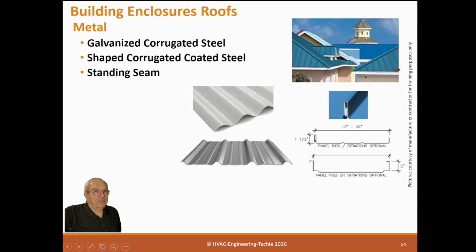They are very durable except for hail. Now, hail doesn't damage the metal, but what it does is it damages the surface. When it hits, it forms a little dimple. And that dimple will separate the coating from the steel. And so eventually the coating will come off and it'll be susceptible to the ambient. So hail can destroy a metal roof.